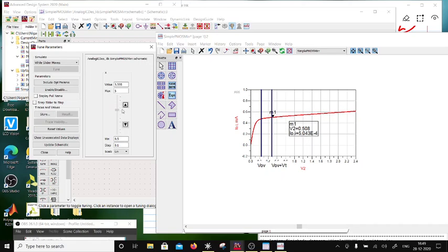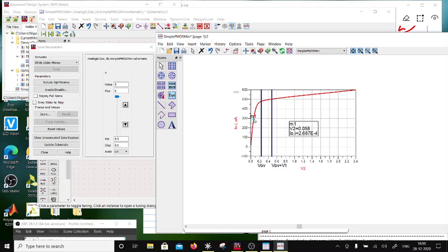If you scale L and W at the same time, so basically if you increase L, the output resistance of the current mirror, or the output device, goes up, right? So now it has very little dependence on the output voltage. It is still going to mirror 1:10 roughly, right? So you understood, we have to increase the output resistance of the current mirror somehow, so that V2 has no bearing on the ratio 1:10.